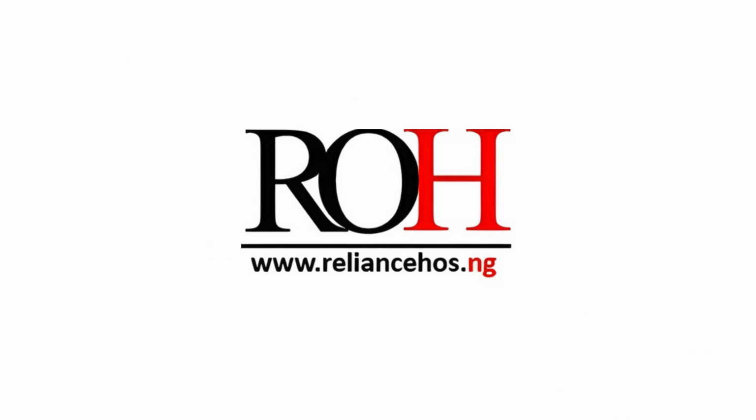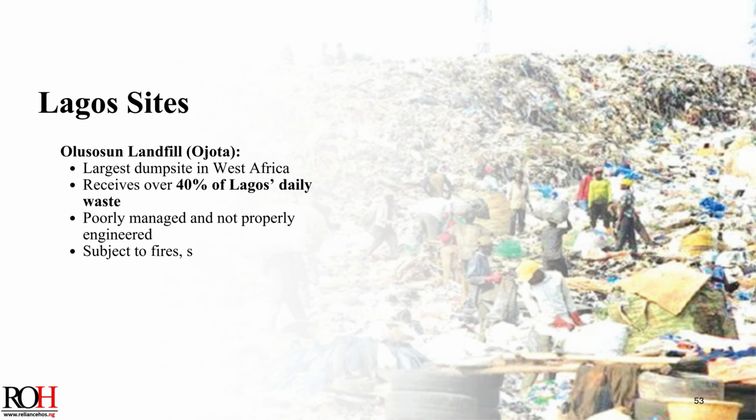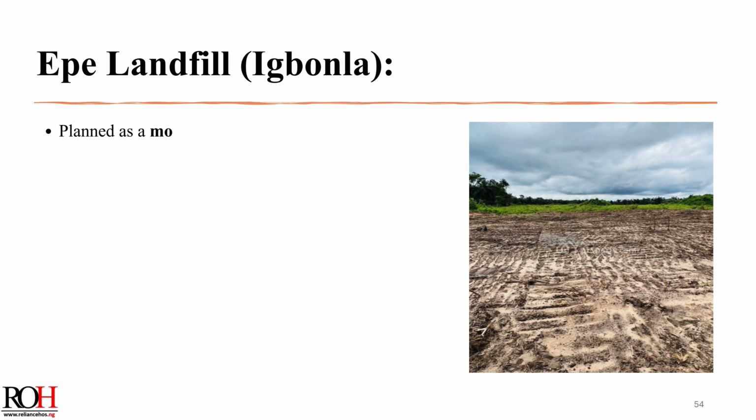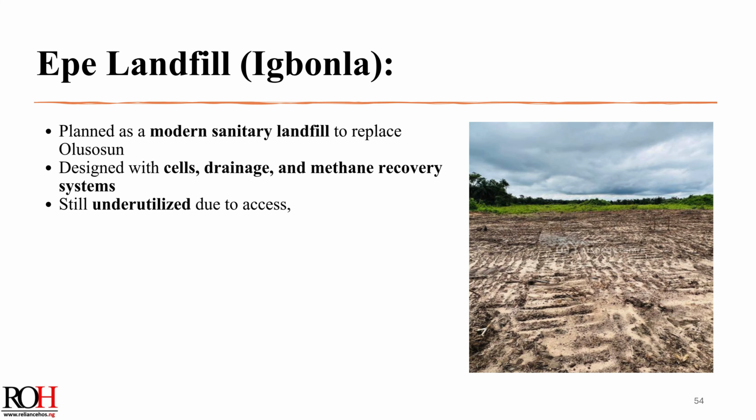Lagos sites. Olusosun Landfill, Ojota, largest dump site in West Africa, receives over 40% of Lagos's daily waste. Poorly managed and not properly engineered. Subject to fires, scavenger activity, and environmental hazards. Now approaching full capacity. Epe Landfill. Planned as a modern sanitary landfill to replace Olusosun. Designed with cells, drainage, and methane recovery systems, still underutilized due to access, lack of coordination, and low public awareness.